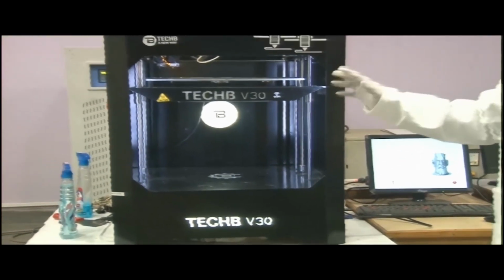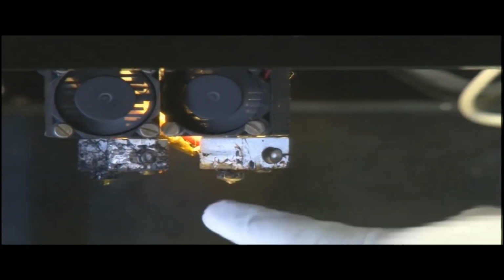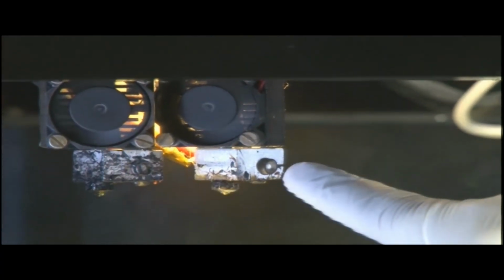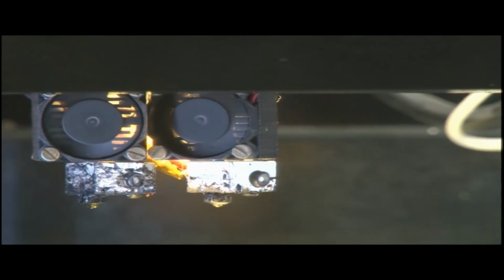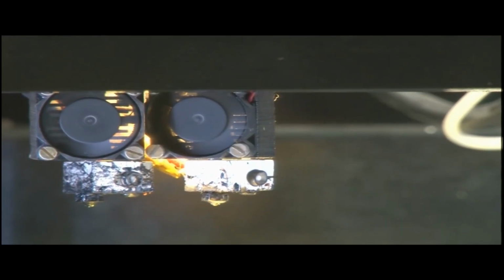So there are two nozzles, one for the model and one for support. If any profile or geometry has a taper of more than 45 degrees, we need to provide support, like I discussed. Then the two nozzles will automatically activate, and that will provide support to produce the final model that we need to obtain. All this feedback is given to the head with the help of software that will be described later on.